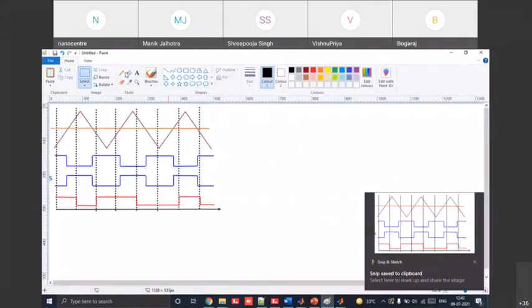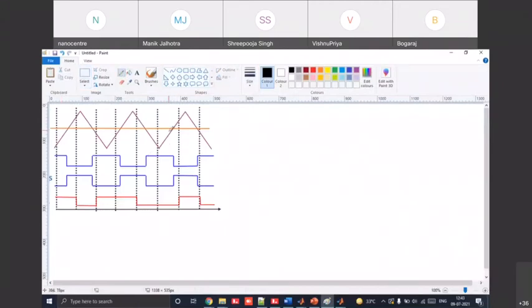What I'm trying to say is that I'm focusing on these two time steps. We can have any two time steps, in fact, because the time remains the same. So within the RT events block, if we just open this RT events, there is this option of how many events we want to capture. We can have a maximum of 0 to 255 events. What it means is, within two time steps, how many events are we expecting?